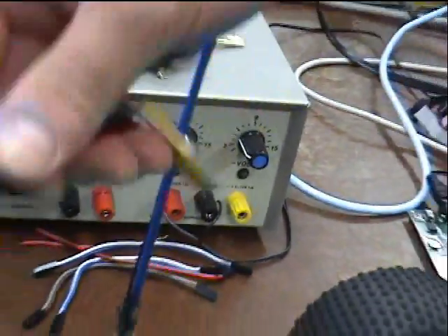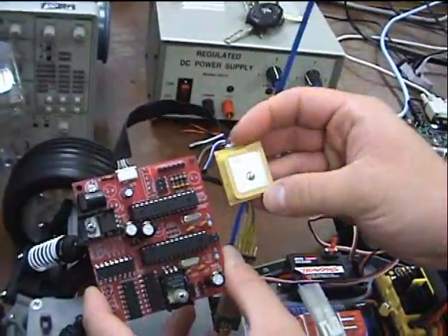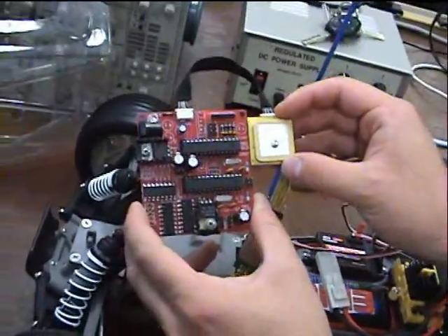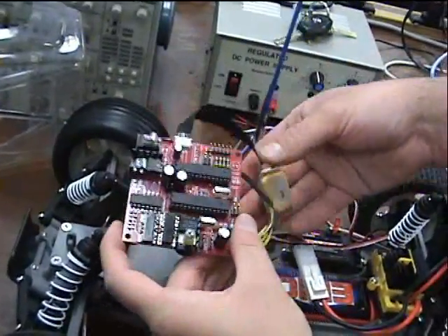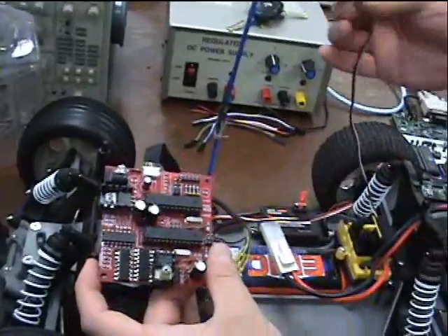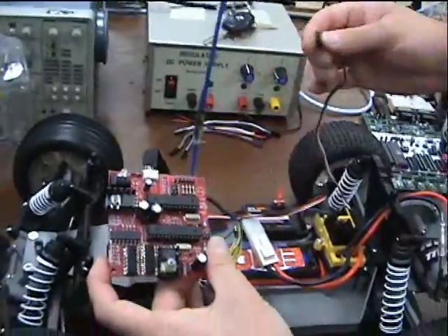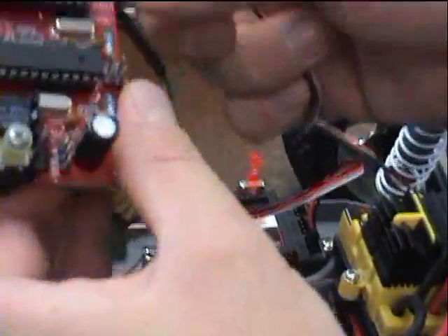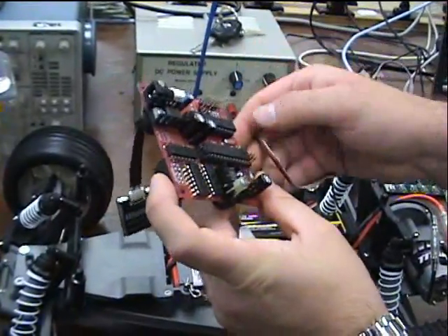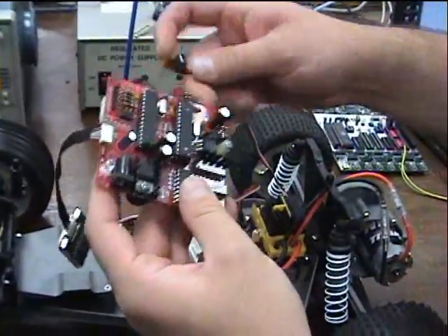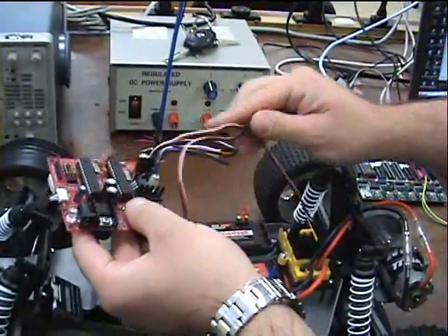The new version of the GPS is much smaller and provides around 5 samples per second. The car is controlled by PWM signals, which attach from the original remote control's speed controller to the car. And where's this? Where's it? Right here. Just like so.